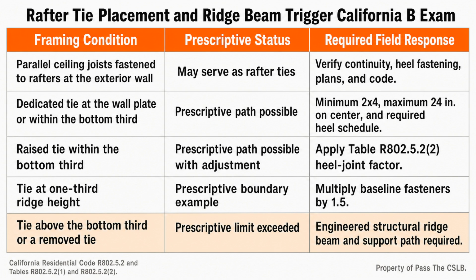I do not substitute a familiar connector merely because it looks close. This connection between ties and load path matters because the forces are different but coordinated. The rafter tie handles the horizontal component created by gravity in a prescriptive roof triangle. The collar tie handles separation at the ridge from uplift. The roof-to-wall and wall-to-foundation connections carry uplift demand through the building. Each component has a defined place in the force path.